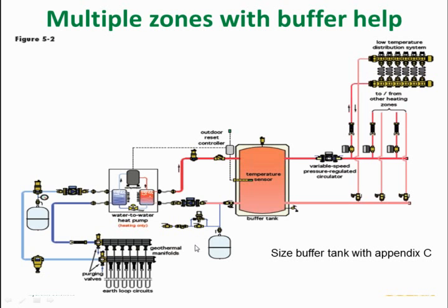One of our boiler trim packages here could be used on this side. Even though it was called a boiler trim package, it could be used on a geo system. It gives you the expansion tank and the fill valve and the connection check valve, fill valve, backflow preventer if you want. It just makes it real simple for you to get to all that in one box and put it in there. So let's see, what else did I want to talk about on here?